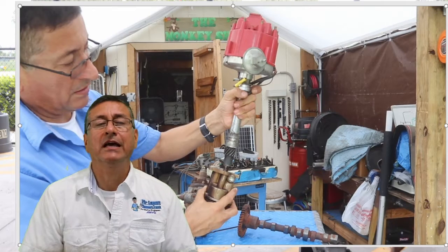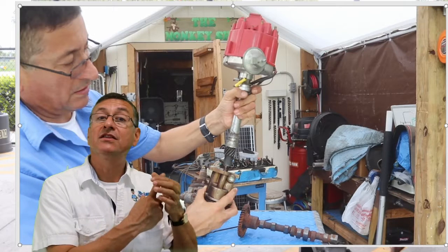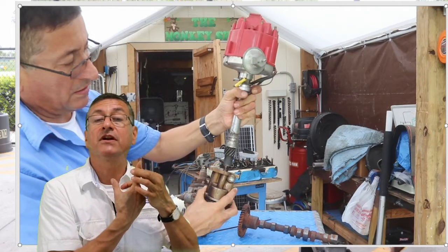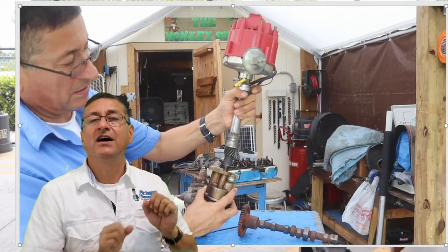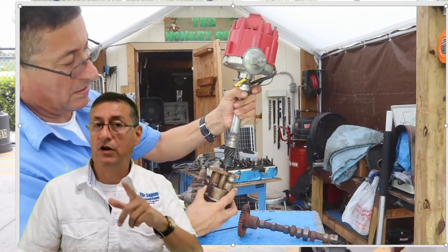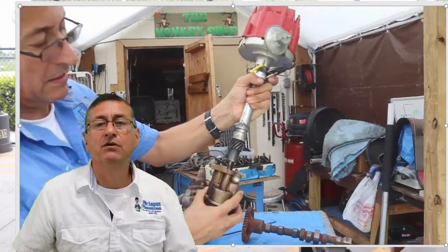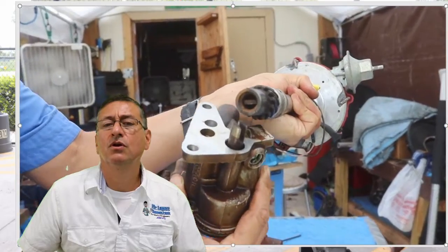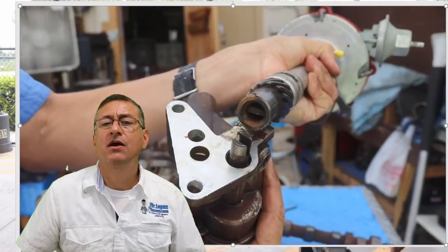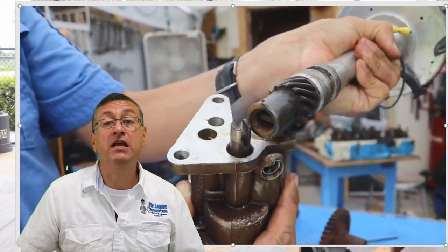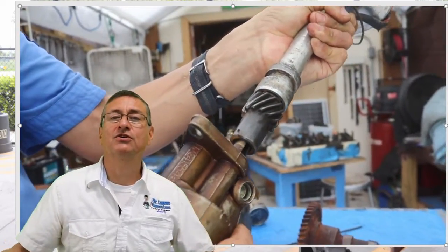In this particular example, the oil pump engages the shaft of the driver gear, which has a slot, and the slot enters the spring on the shaft of the distributor for gasoline engines. You can see in the picture, like the video, those elements engage one into the other, and when the distributor is spinning, the oil pump is running and sucking oil.